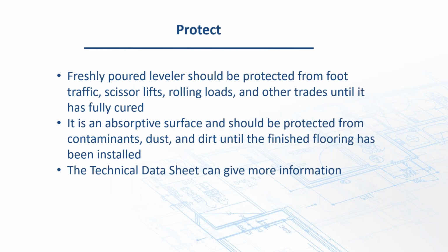And protect it. These materials are not concrete. They're cement based, but they're a different density. If exposed to heavy road traffic too early, it can create some ruts in it. Make sure it's protected. And not to mention, you're going to be putting finished materials over it. You don't need overspray from the painter that just finished the drywall when you were gone last night. Try and keep foot traffic off it if you can.